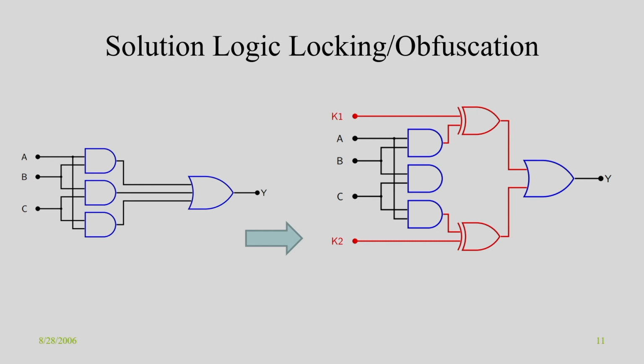So, what logic locking says is this: I will give my IC to you, I will give my layout to you, you can do the reverse engineering, you can extract the netlist, you can produce multiple copies, you can duplicate things and sell them in the market, but that particular IP will not work, right. Even if you have the whole netlist and produce the IC, you can't use it, right. That means I give you my intellectual property, you can do IP piracy and overbuilding, but that won't be useful, right. That was the motivation of logic locking.